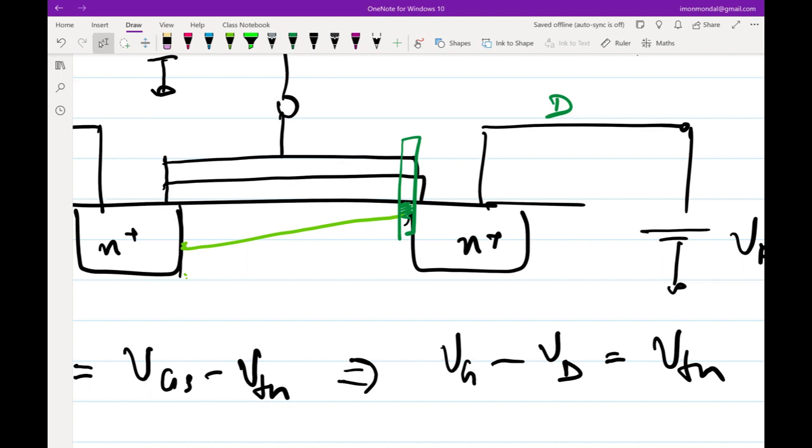So at this junction, when we reach this condition, we say that the channel is pinched off. When the channel is pinched off, essentially the profile of this channel charge will slightly change again. It will go to 0 under the pinch off condition.